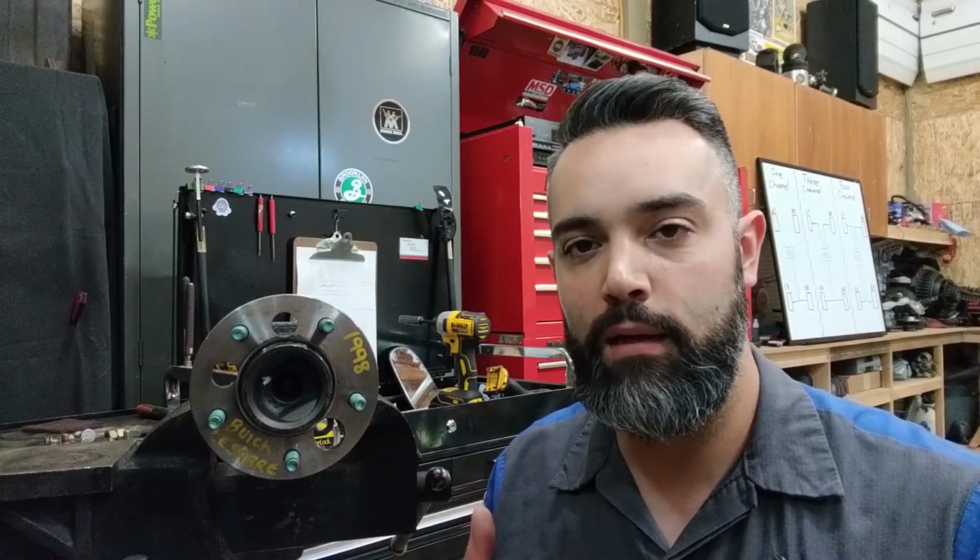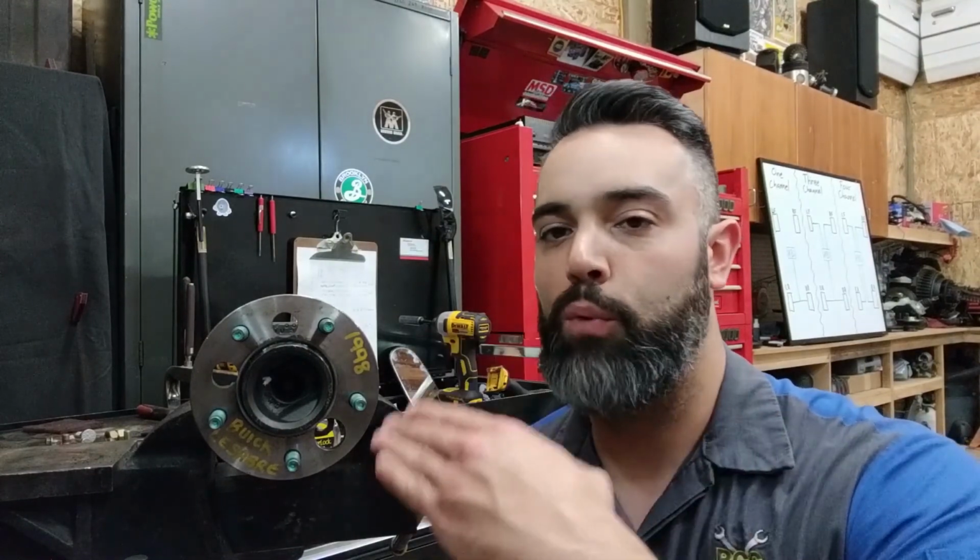Now let's talk about how that affects the braking of the vehicle. So what is the control module going to do with this information, and how does it work? Well, control modules operate off of inputs and outputs. They have algorithms built inside of their programming to interpret information coming in, process that information, and then send information out to other components. So inputs are things like wheel speed sensors. The computer cannot control what the wheel speed sensor does. The computer can control other parts of the circuit, but it has to depend on information coming from the wheel speed sensor to determine what it needs to do.